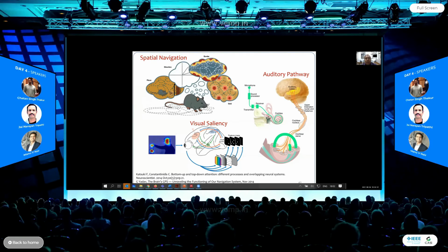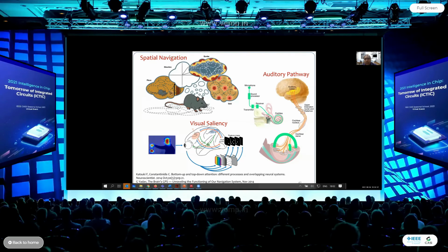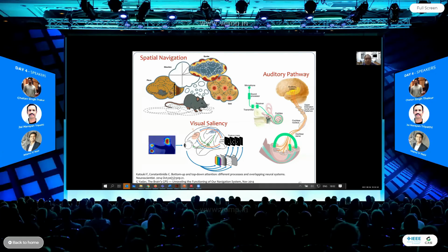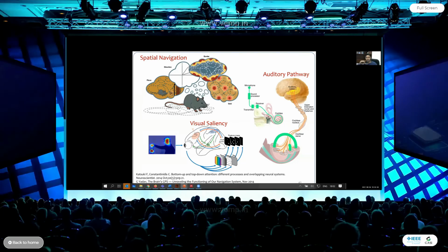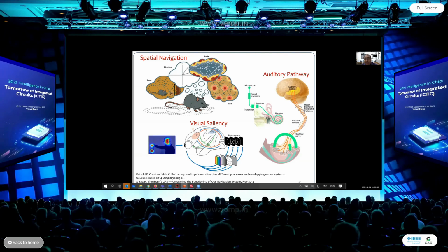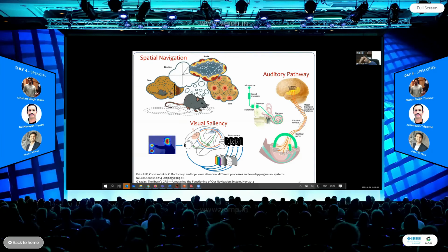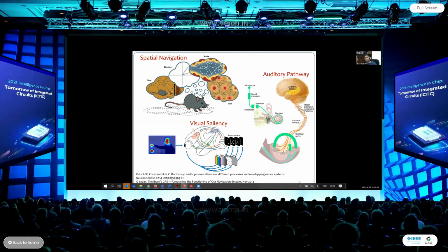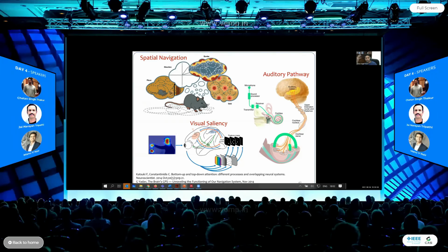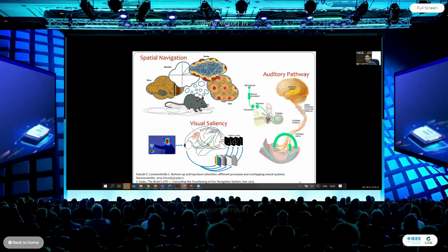So at the end, you do still have the vector multiplication going on in the Cochlear model? Yeah, because it's maths in the end, right? So basically, the same things that you would use to build deep learning, you can use some of those there as well. Correct. Another thing is, if you're using deep learning in the pipeline along with the Cochlea, you can in fact replace the MAC operations with some approximation. As long as it has this resonating structure, the rest can be taken care of by the learning stage.